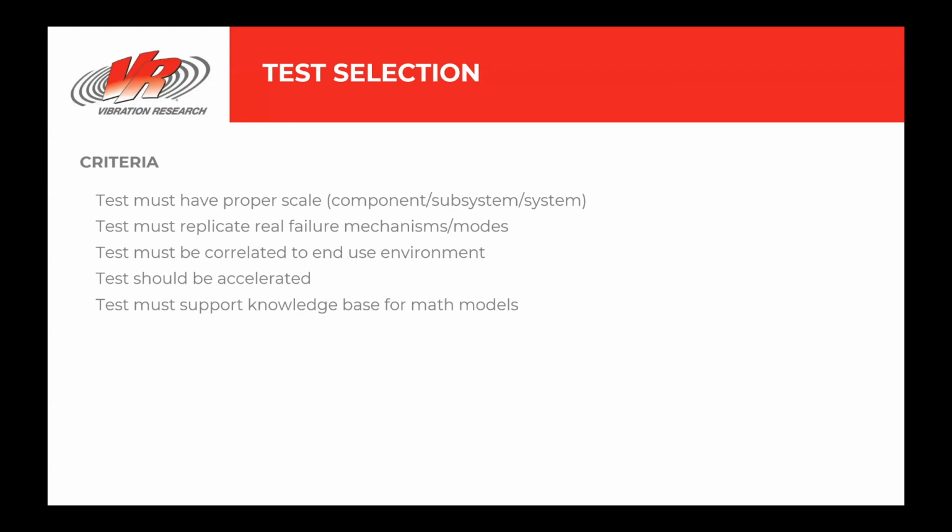Sinusoidal vibration testing applies vibrations with a constant frequency and amplitude, whereas random vibration testing can simulate real-world vibration conditions by applying a range of frequencies simultaneously. These are appropriate for our design validation and our process validation. STAG, which we talked about earlier, the sine tracking, analysis, and generation, is appropriate for products that have rotating components. Highly accelerated stress screening is used once the product is in production to assure ongoing quality.